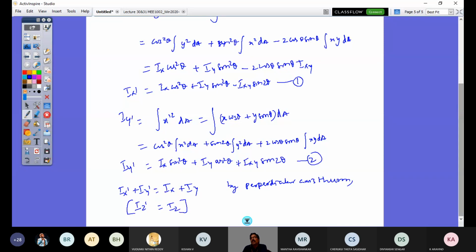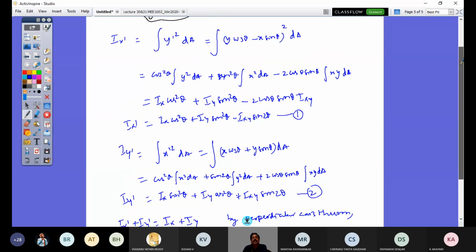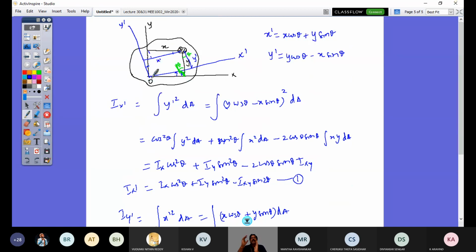So what do you understand? If I have my rectangular section and I rotate my axis set, holding the xy plane only tilted and the z axis orientation not changed, then the polar moment of inertia of the section about the z axis is not changed.